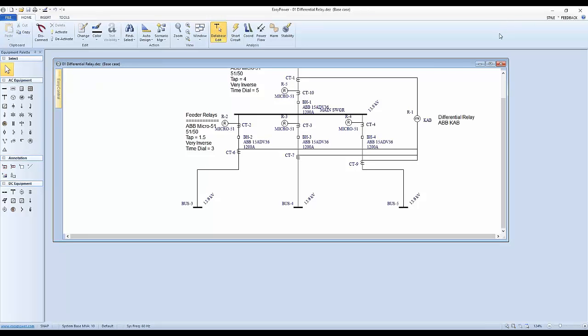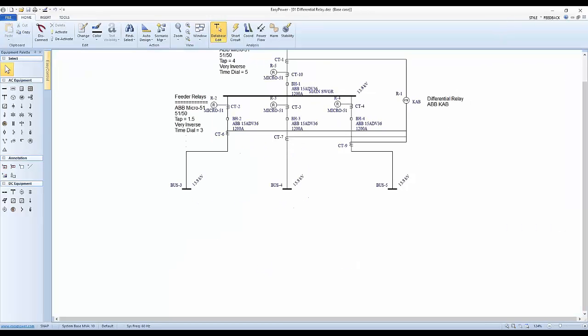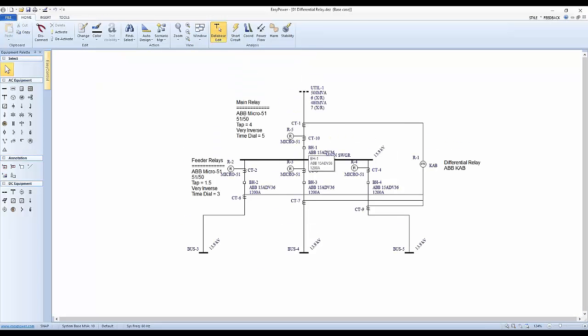And what you'll notice here is that we have overlapping effects. In this one line, we have the individual overcurrent relays for the individual lines, the main coming in and each of the feeders. As we set these up, they will give us a trip of, in this case, the main breaker if we have an overcurrent detected on the main line coming in. Likewise, if we have overcurrent on any of the outgoing feeders, it can isolate that individual feeder.